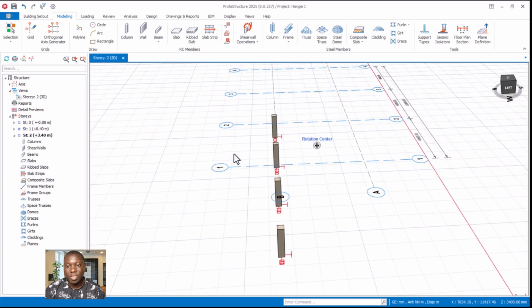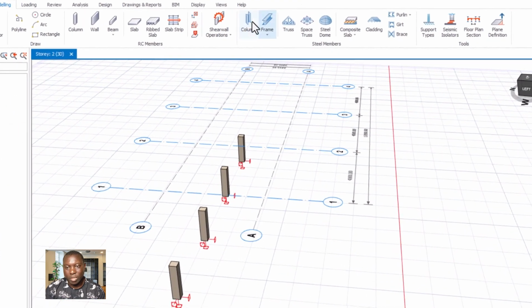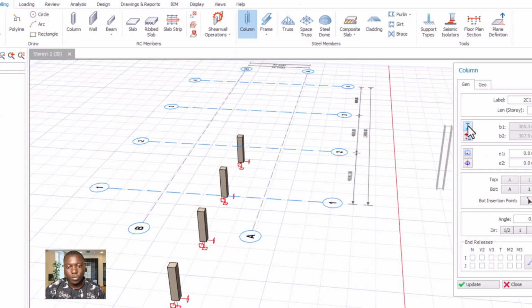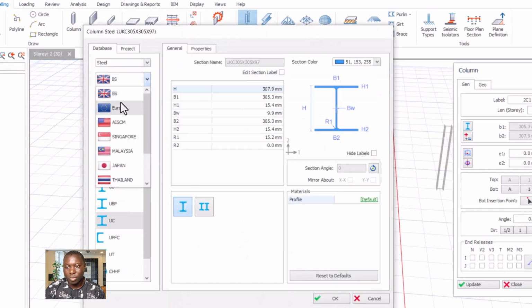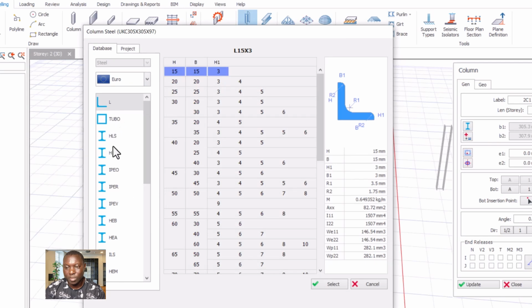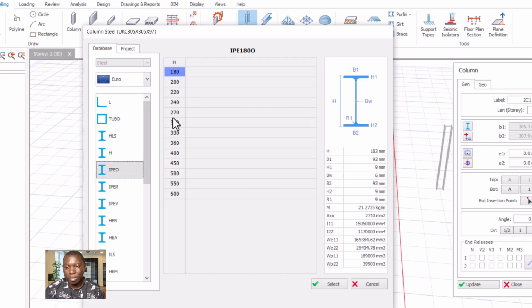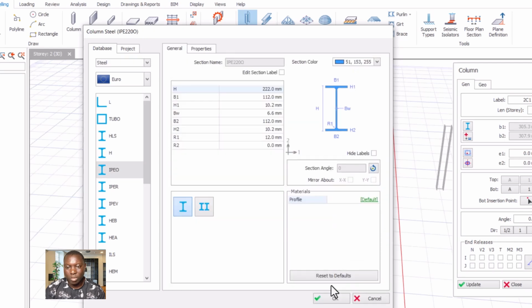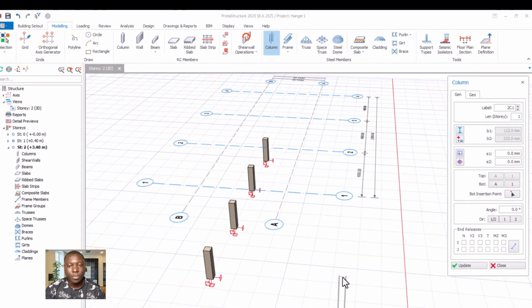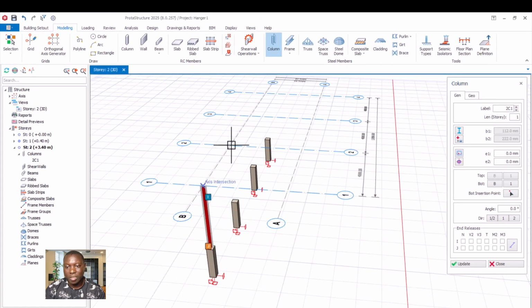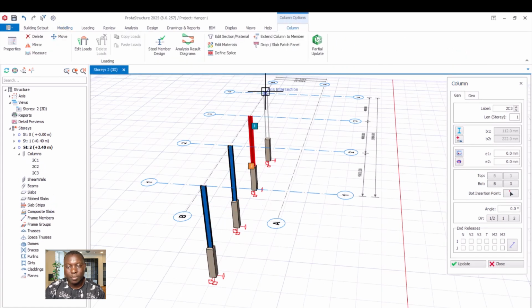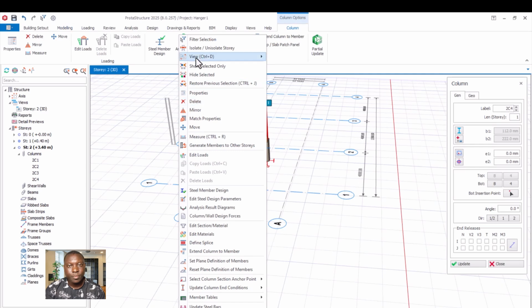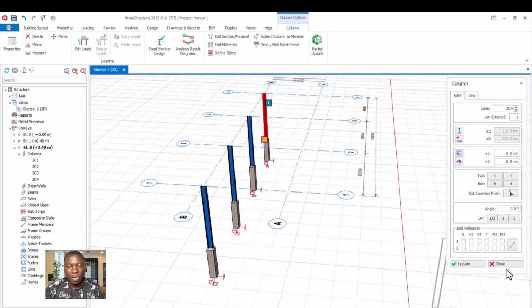So we place the steel stanchion, select on it, and then we choose the sections. We are going to be considering Eurocode database sections, and then we use IPE 220. Select that, click on the OK option. I pick out the grid line intersection right there to place it just like this successfully. All right, I will close this dialog right away.